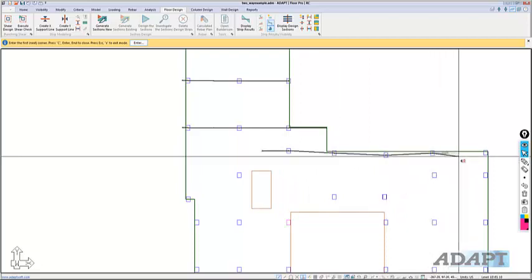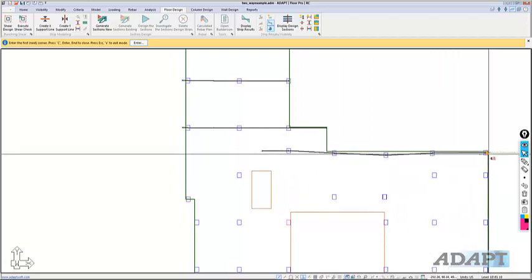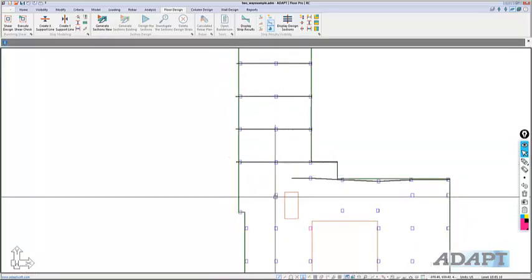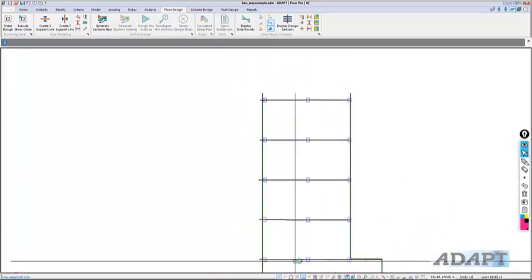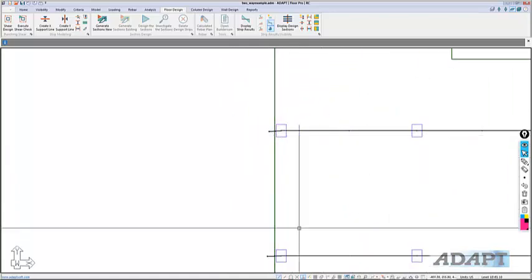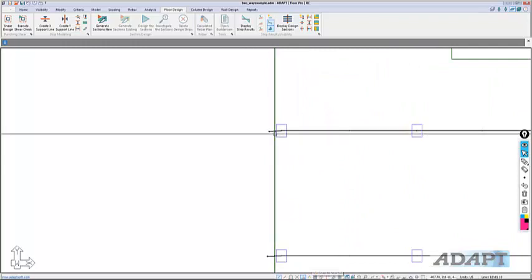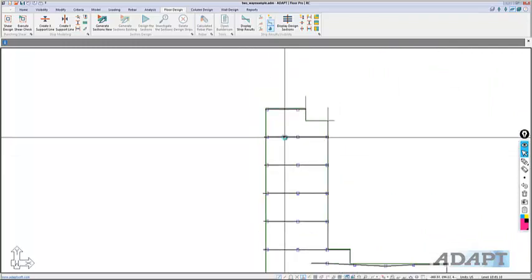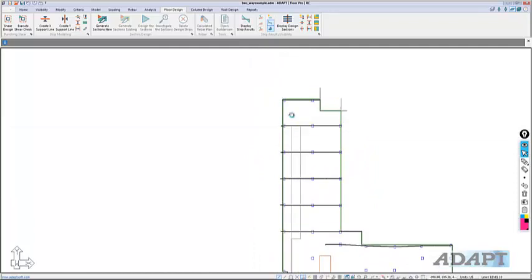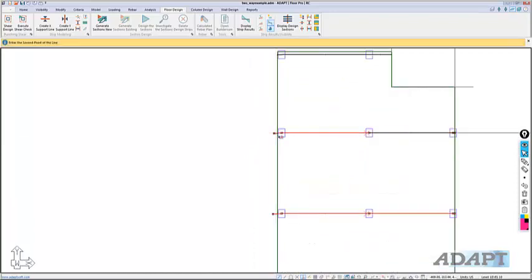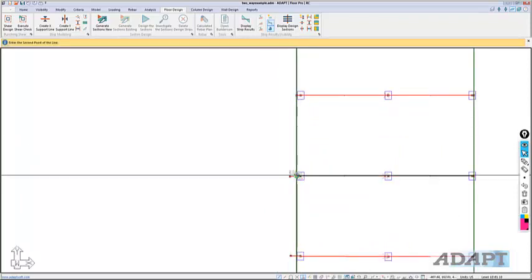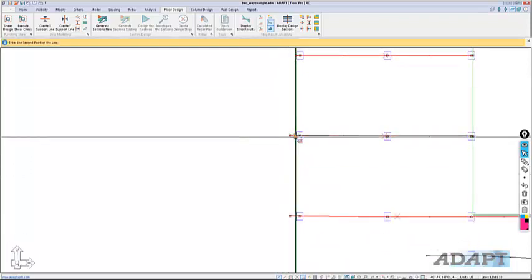This will show the use of the splitter tool as it's currently constituted in the program. So if we have a support line that extends out of the slab, the reason I did that was just ease of use. I don't have to zoom in, turn snap to nearest on, and then come back and snap on that edge of the slab. I can just select these now and use snap perpendicular just to readjust those back to the edge of the slab.